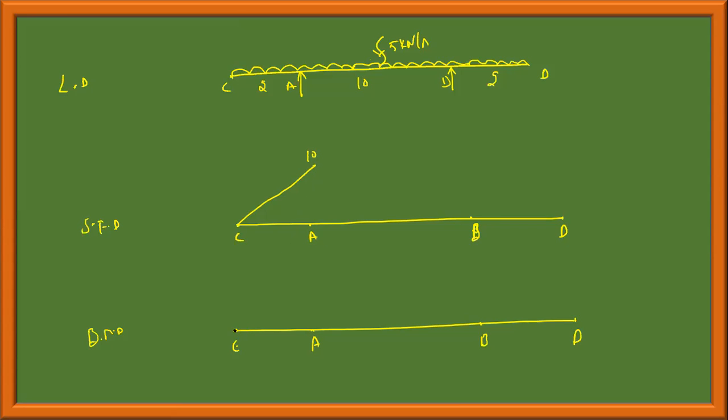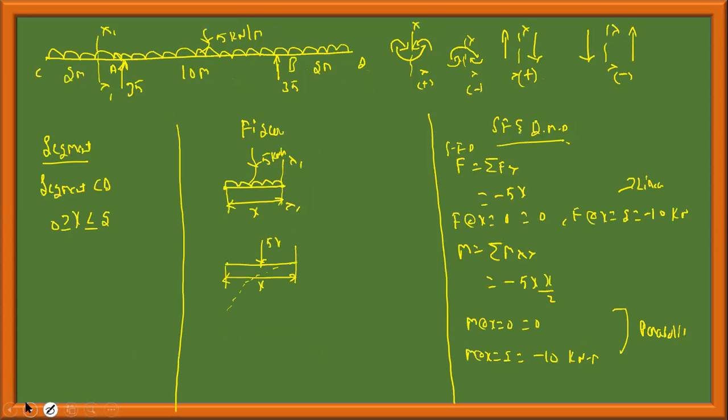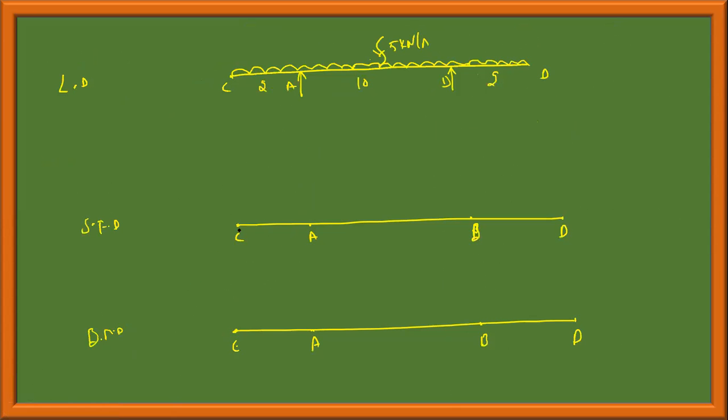Bending moment at x equal to 0 is 0. At x equal to 2, it is minus 10. This has to be downwards. Shear force, what we got, minus 10, this should be downwards. Bending moment also minus 10, this should be downwards. Shear force is linear, bending moment is cubic. How I plot the curve, you should know. And the shear force should come like this, up to here like this.